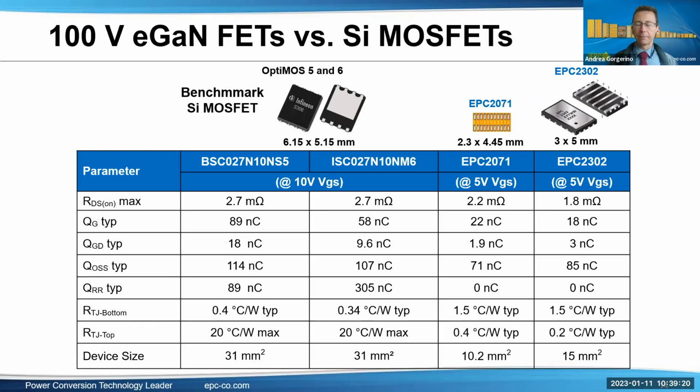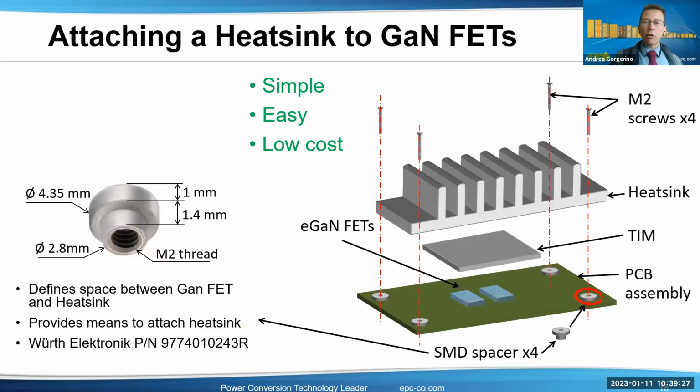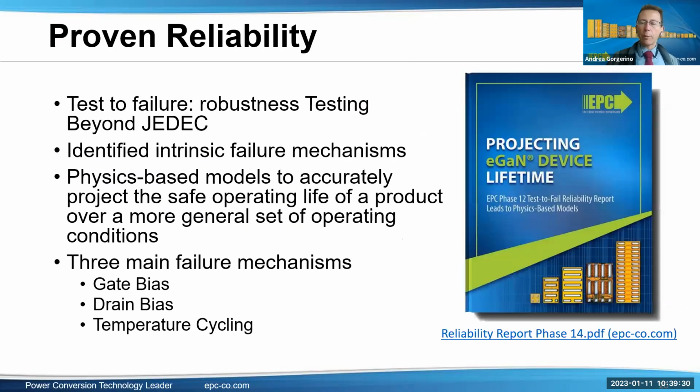Okay. Can you show or give a link where the application of underfill is shown? Yeah, so I think the most information on underfill is shown in the reliability report. There's a whole section on temperature cycling, underfills. We've tested several different kinds. Some actually make the performance better, like the ones I showed in the chart. Some make it worse. And we have some guidelines on how to pick the right one. It has to match the CTE mainly of the board and the device. That's typically the criteria.